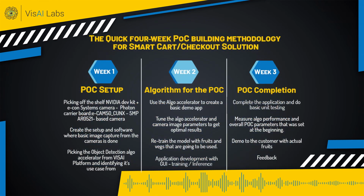And from there, we went ahead and decided on the exact hardware in week 1, where we finalized on the Photon carrier board. We took that off-the-shelf Nvidia dev kit, along with one of e-con's cameras, the e-CAM50_CUNX, which is a 5 megapixel camera, which we attached to the Nvidia dev kit. Because this is a ready-to-use development kit, it has the camera running on it already. You have all the software which runs on this dev kit already, and you could get the camera streams to memory with an application straightforward.